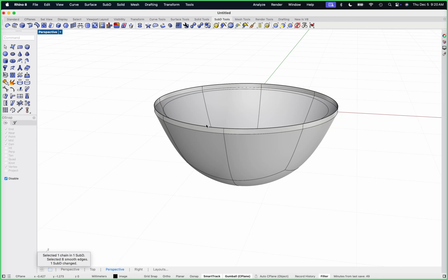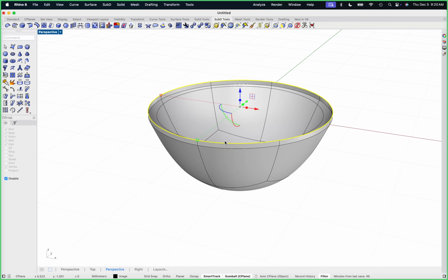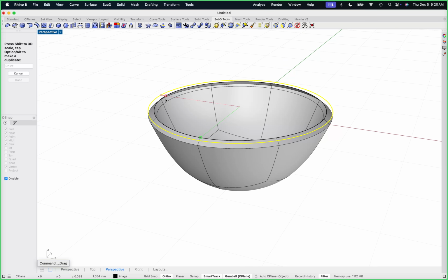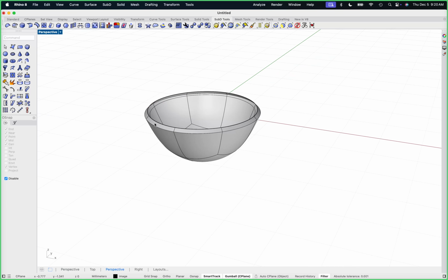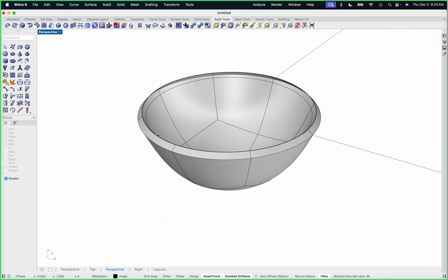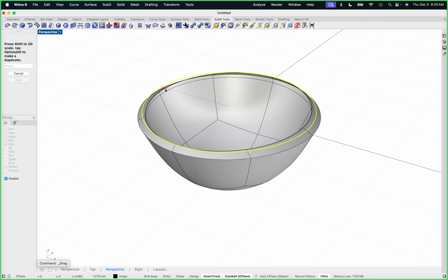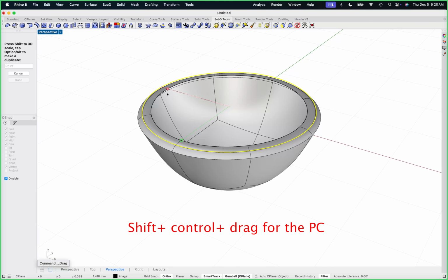And then I'm going to grab this, and I can shift drag on any scale handle, and I can kind of get my little flange. And then I'm going to start dragging a handle. I'm going to hold down shift, and then I'm going to hold down command, and that's going to extrude a face. Little finger jujitsu going down there. So shift, drag, command. You can see that that's going to extrude a face.